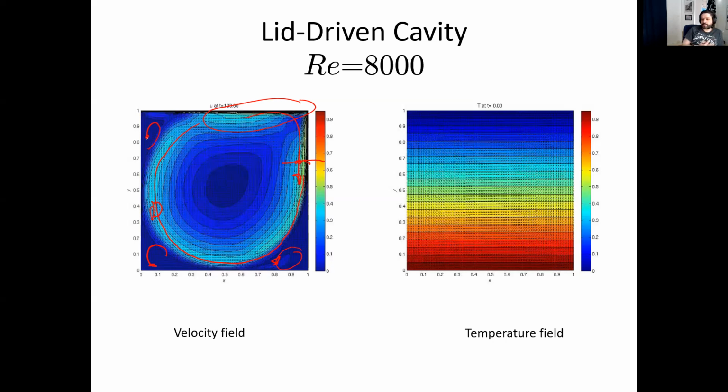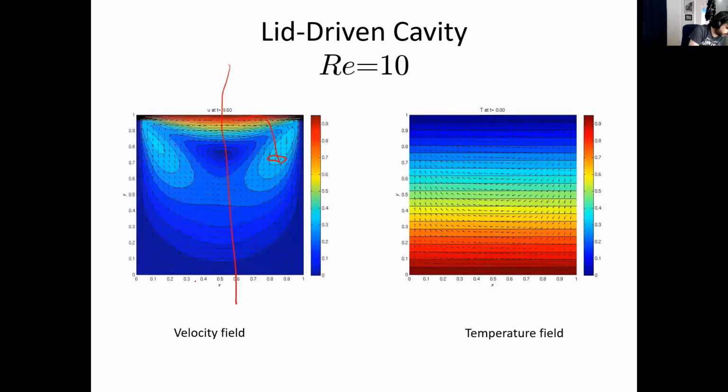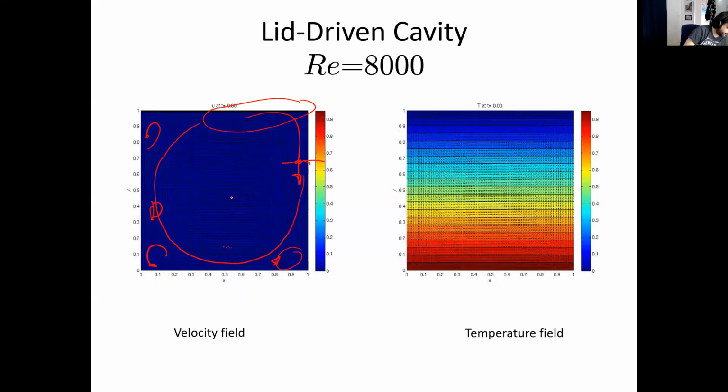So this is the typical way that a high Reynolds number flow would look: thin boundary layers, a lot of unsteadiness. So it will take a long time until you actually reach a steady behavior. Also, maybe you can see it, I also needed many more grid points here compared to the previous plot, which was for the lower Reynolds number, where the spacing between the grid points was much larger. Here, I need many more grid points in order to be able to resolve all the flow structures.